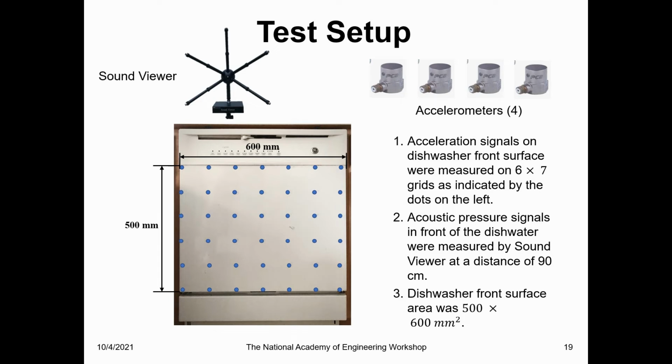Here is the test setup for a dishwasher. Four accelerometers were used to measure the surface acceleration signals on the dishwasher front surface over 6x7 grids. Acoustic pressure signals were measured by a SoundViewer at a distance of 90 centimeters.